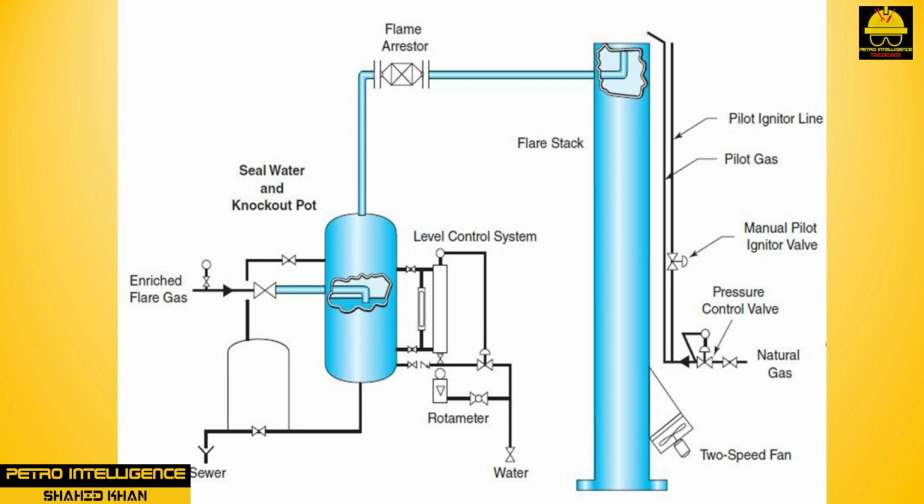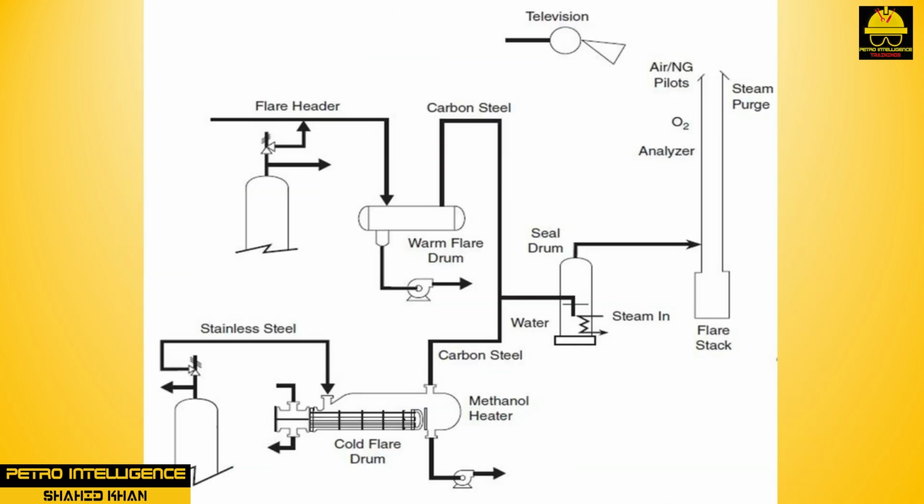Most process units are lined up to safety relief valves that lift when specified pressures are exceeded. These safety valves discharge into the flare header. Unexpected process upsets are dumped to the flare system as a last course of action.